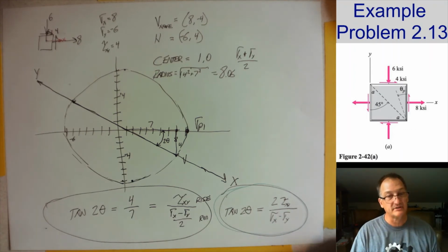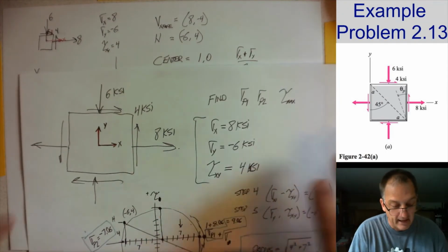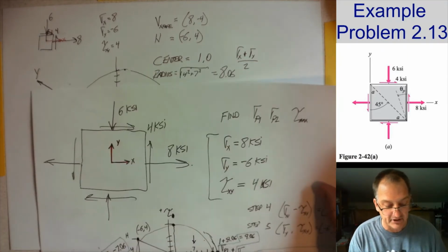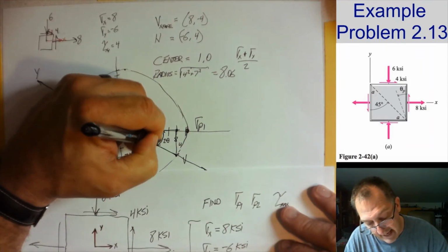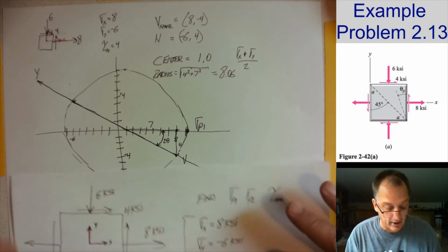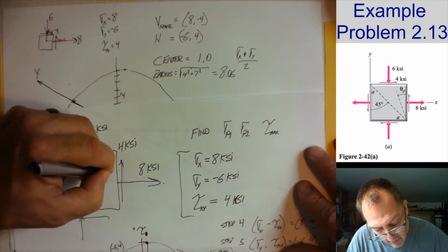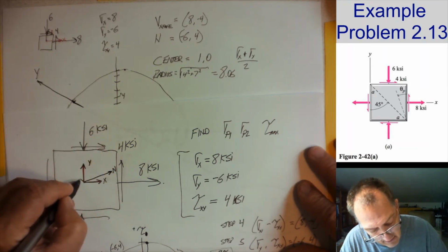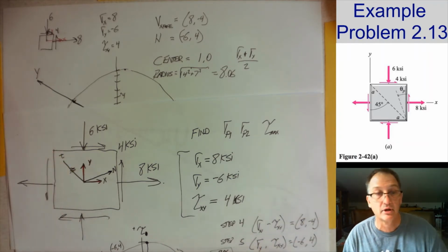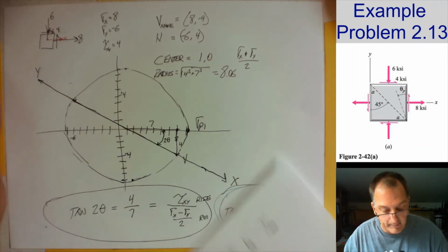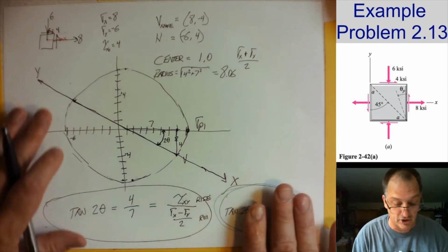That's where this Mohr circle stuff's kind of cool. So if I go back to a big picture and I say, hey, how do I get to the principal stresses? Where are my principal stresses going to occur? Well, I don't know what that angle is exactly. I mean, I could calculate it, but I do know that if that's my x, that's my n, and that's my t. That should be farther that way. That's a sloppy drawing, but I know that n is going to be up by exactly half of what this is up. Now, that again is challenging because we've got a coordinate transformation.